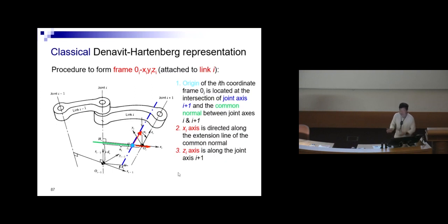And then after that, you have to determine the z-axis. The z-axis is probably the simplest to identify. The z-axis is always along your joint axis. We mentioned earlier that every joint has a single axis, so with that, you will be able to easily identify the z-axis. After you have your z and x, you can determine your y according to the right-hand coordinate system.